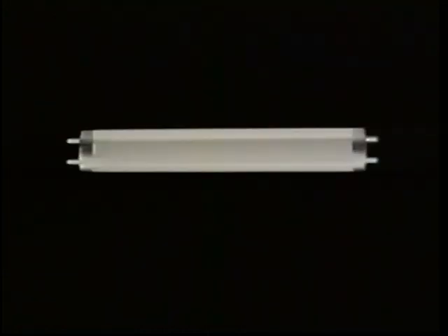Sometimes, though, it's difficult to maintain the proper temperature to operate the lamp correctly. In these cases, the selection of the proper lamp and ballast can overcome the problem. Occasionally, humidity can cause rapid start and instant start lamps to be hard to start. To combat this, a thin coating of silicone is applied to the lamps to aid starting. Because of their higher starting voltage, preheat lamps usually don't have this problem.